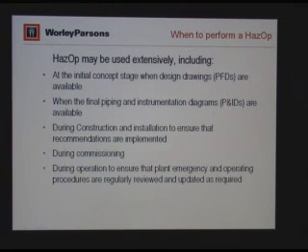HAZOP can also be used during the construction and installation stage, just to make sure the recommendations are all implemented. It can be used during commissioning too, and because it's an operability study as well, it can be used during operation to ensure the plant emergency and operating procedures are regularly reviewed and updated.